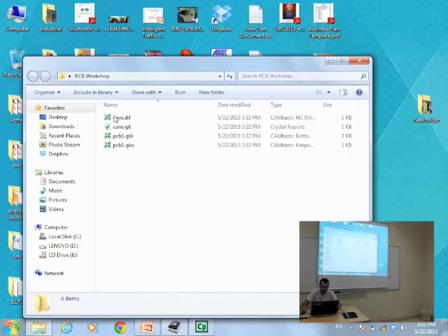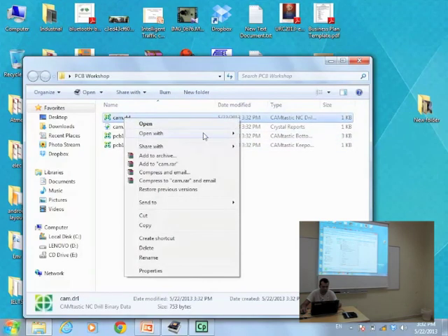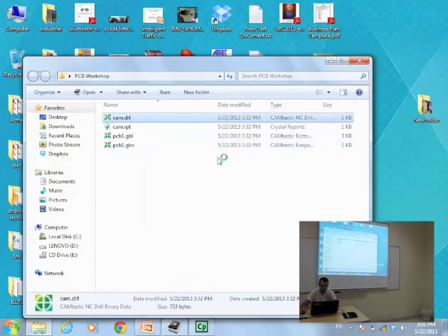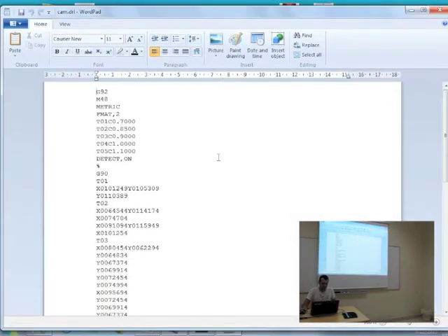Here I have some text files that do this. They are actually text files. Let me take a look at it. This is the thing. G92 means my location is absolute, meaning give me a point, so from that place I can go everywhere I want.